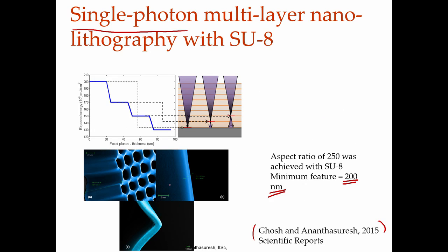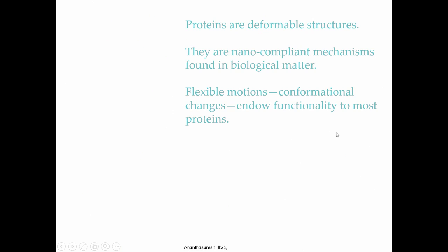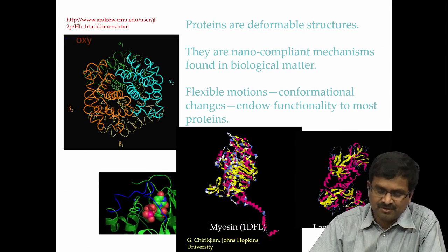This line that you see here, that is 2 microns. So, clearly the height of this is much more than that, whereas here, this little line that you see at the bottom is 100 nanometers. I do not know whether you can see it, the little line is 100 nanometers, and this is 2 microns. So, 2000 nanometers to 100, you have such a large aspect ratio, and in fact you can go to an aspect ratio of as much as 250 here. Okay.